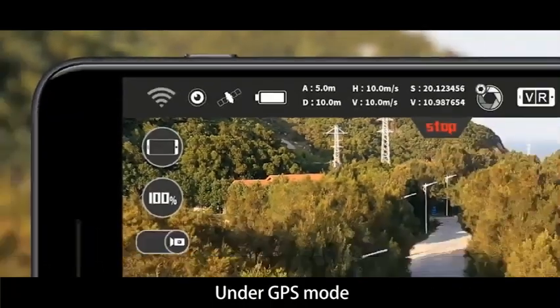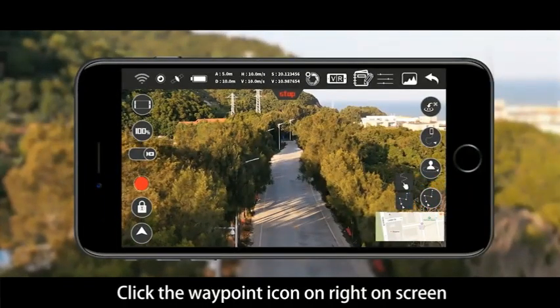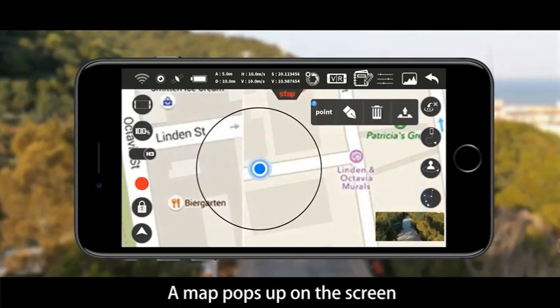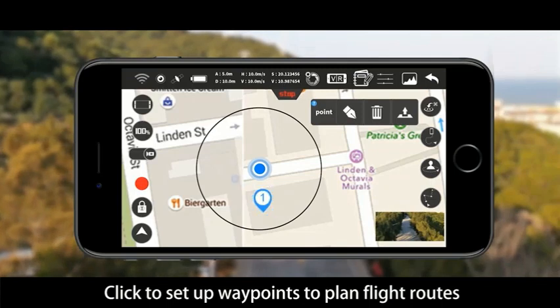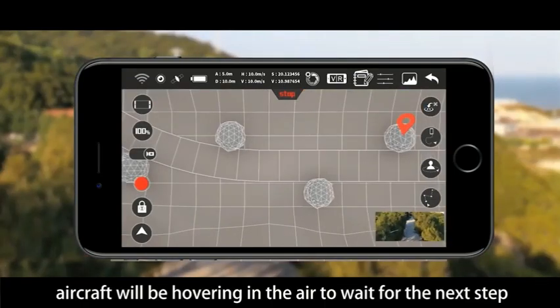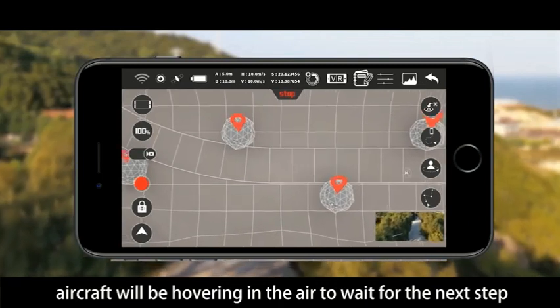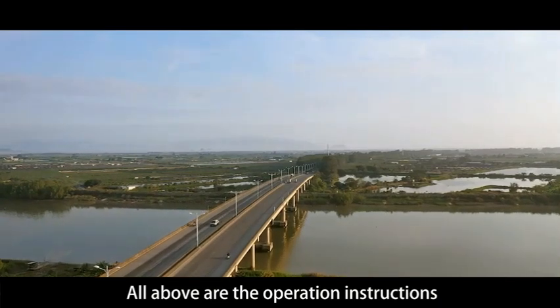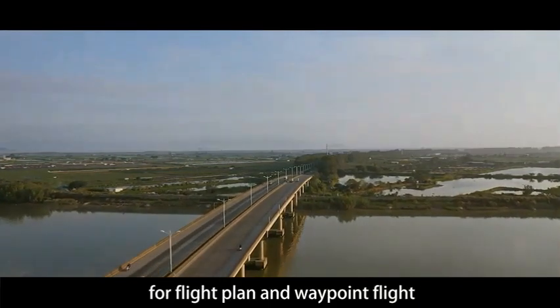Under GPS mode, click the waypoint icon on the right of the screen to enter waypoint mode. A map pops up on the screen. Click to set up waypoints to plan flight routes, and then click the launch button. After finishing the planned route, the aircraft will hover in the air to wait for the next step. All above are the operation instructions for flight plan and waypoint flight.